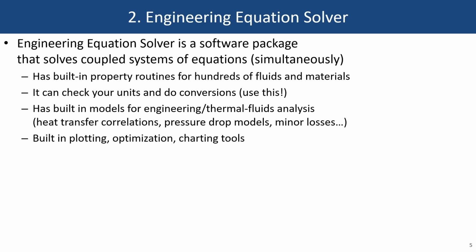If something was listed in kilojoules instead of joules and the solution was off by a factor of 1,000, it could cause very strange issues. So it's a pretty nice tool that Engineering Equation Solver can do conversions for you, and it can give you warnings if it detects that your equations are not consistent in their units. But you have to use that feature correctly.